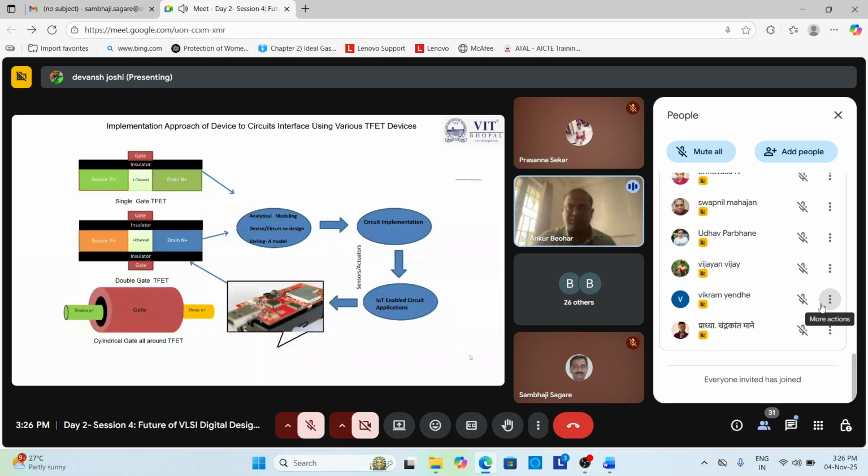The Verilog-A model will also be designed in only one SPICE file, based on the parameter values like the LUT model and all. Once we have the parameters, we replace them with the one file, where, for example, from 0 volt with a 0.02 step size, we have taken the drain voltage extraction up to 2 volt. In this way, if we increment with a 0.02 step size, we have multiple data parameter extractions. In that model, in a single file, we call it through the Verilog-A SPICE file, and then we have a circuit implementation.